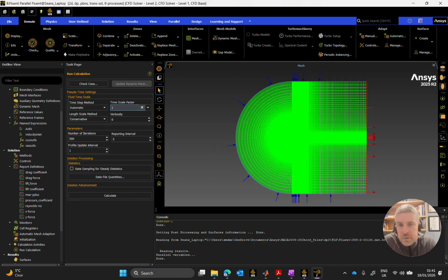I put these into report definitions, as I said, because it might be interesting to try to automate the grid convergence index method within ANSYS itself. You'll see many contributors that are doing the grid convergence index method will take the values out of ANSYS and they'll plant them into MATLAB or into Excel, and they'll do the formula calculations in the external software, and then they'll output their findings from that method there.